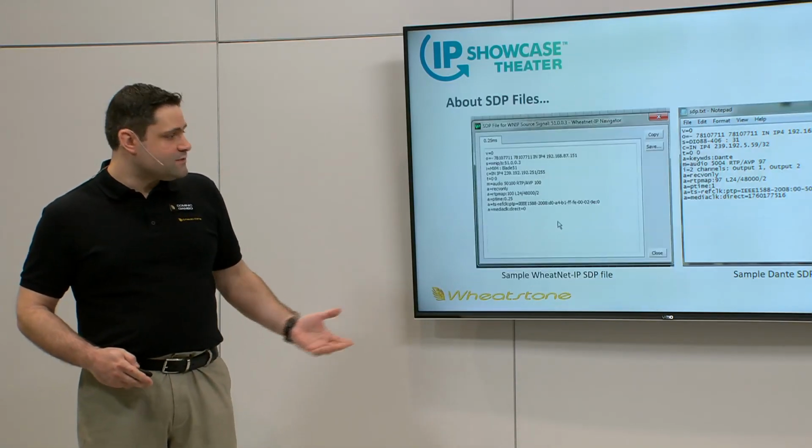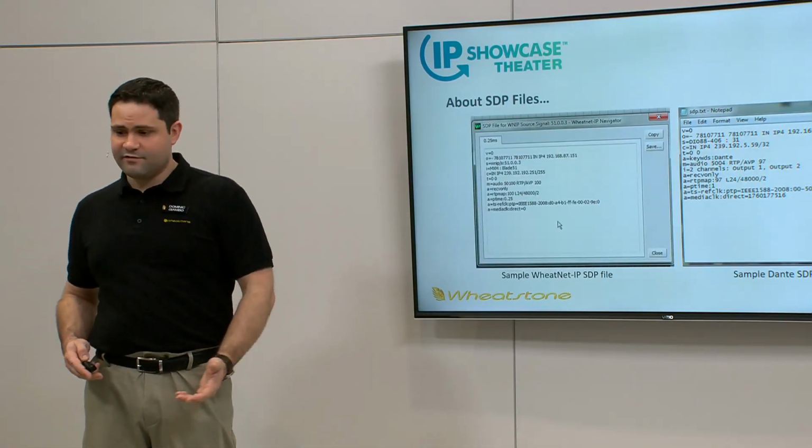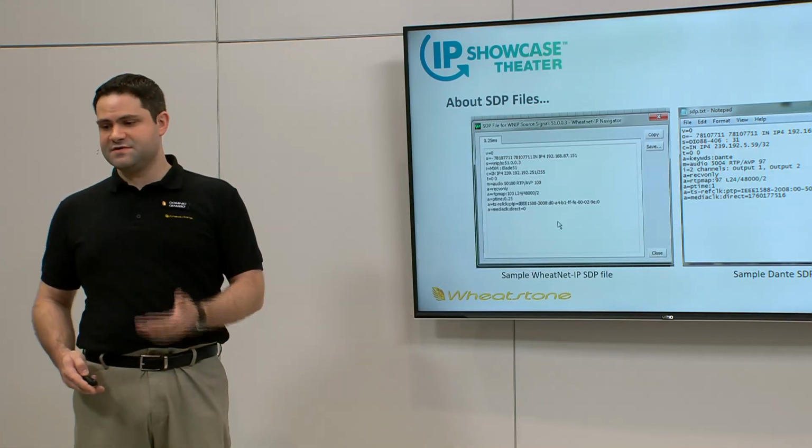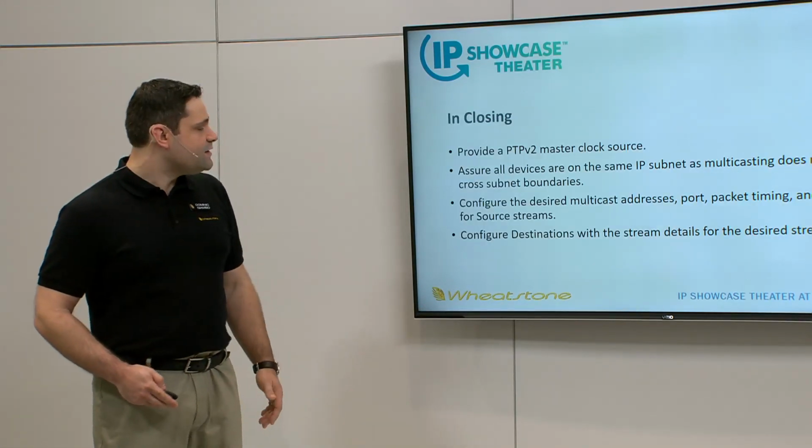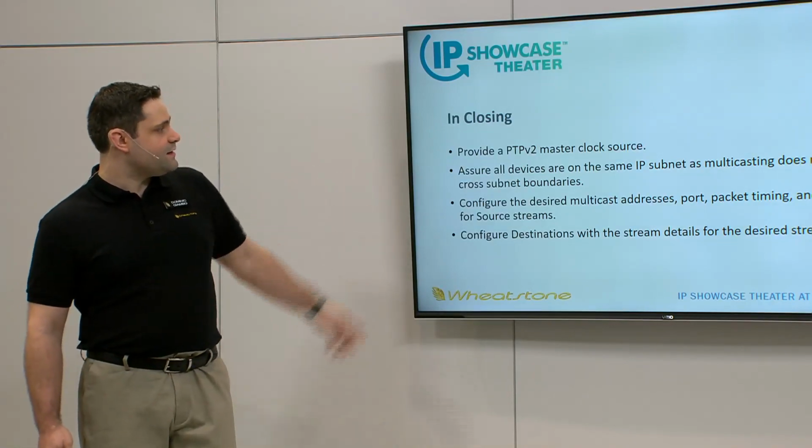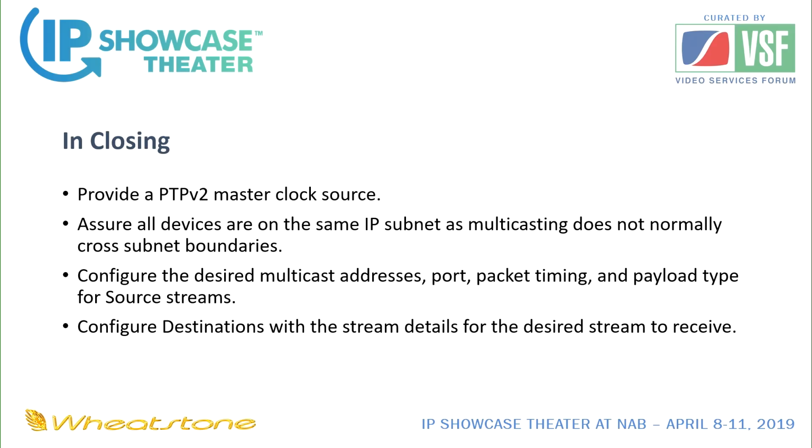With AES67, we didn't lose audio on any of the AES67 devices. There were no clicks and pops. Everything worked cleanly. The main thing to keep in mind, again, we originally tried using some of the AoIP devices as master clocks, and we found that there were clicks and pops in the audio. It just wasn't accurate enough to maintain synchronization. That may change in the future, and certainly some devices could be better than others, but if you use a dedicated PTP clock, you avoid that.